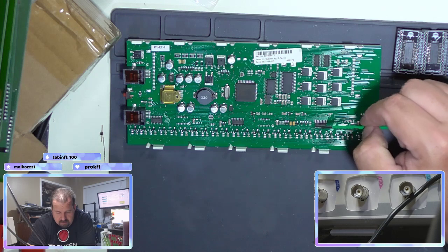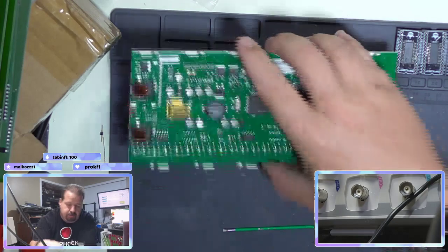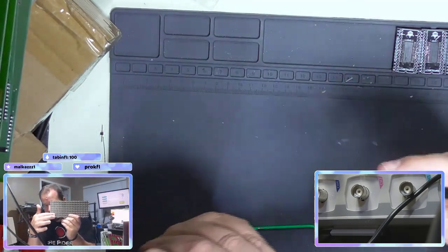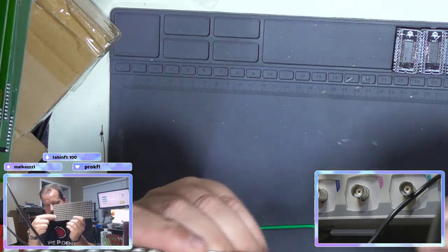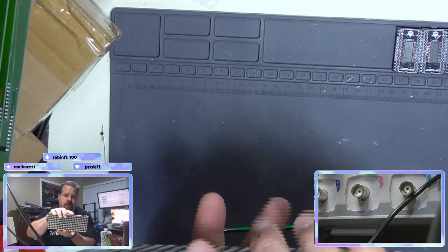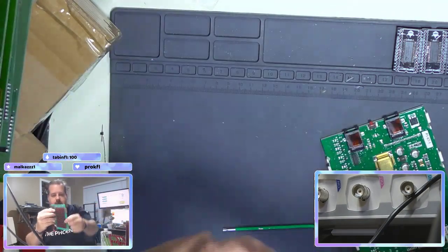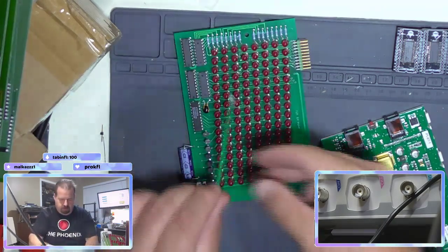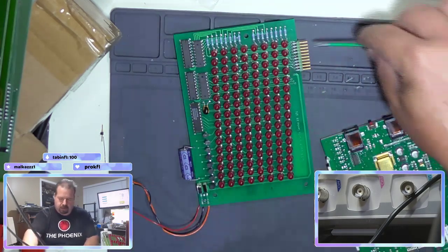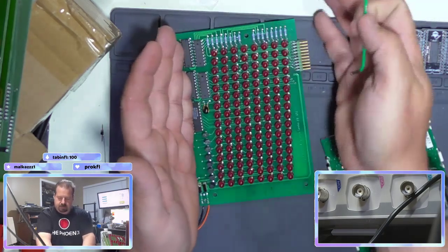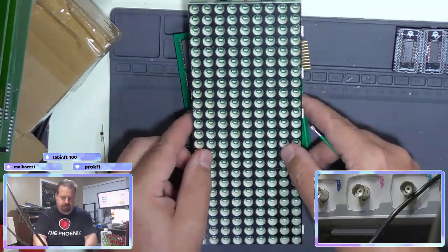Being serial driven means you can drive it probably a little bit faster, and then your persistence of vision is going this way, up or down, which is easier. So we're only having to do 8 going this way. So envision this with this other display. The other displays are drawing in this order, like this. So we're data loading these over an 8-bit bus, and then we're showing this based on an 8-bit bus.